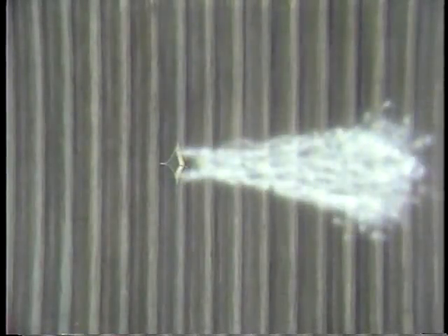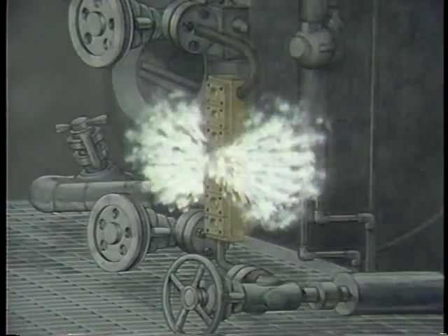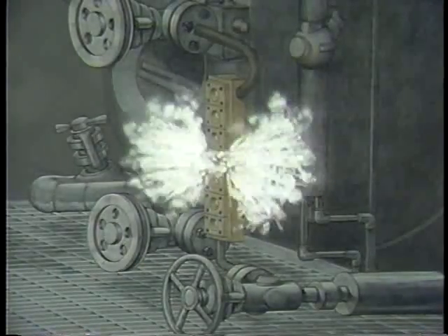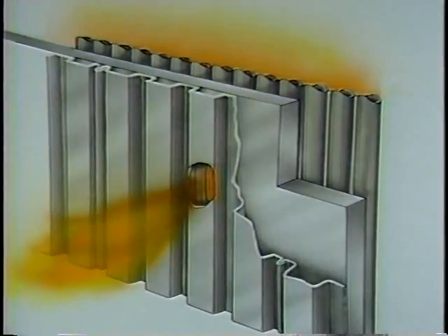In this part of the program, we've concentrated on problems associated with boiler leaks. We've looked at tube leaks and ruptures, which occur inside a boiler, leaks in equipment and components, which generally occur outside the boiler, and leaks that occur through the boiler casing. For the most part, an operator has two choices for dealing with boiler leaks. If possible, the operator should isolate the leaking component and continue operating until the unit can be scheduled offline for maintenance. If the leak is severe enough to jeopardize the boiler flame or the operation of the plant, then the unit must be shut down immediately.